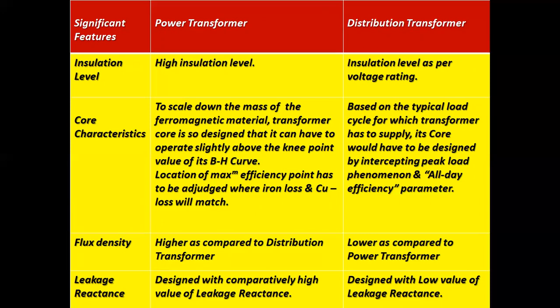Flux density. For power transformer, higher as compared to distribution transformer. Distribution transformer, lower as compared to power transformer. Leakage reactance. For power transformer, it is designed with comparatively high value of leakage reactance. In case of distribution transformer, it is designed with low value of leakage reactance.